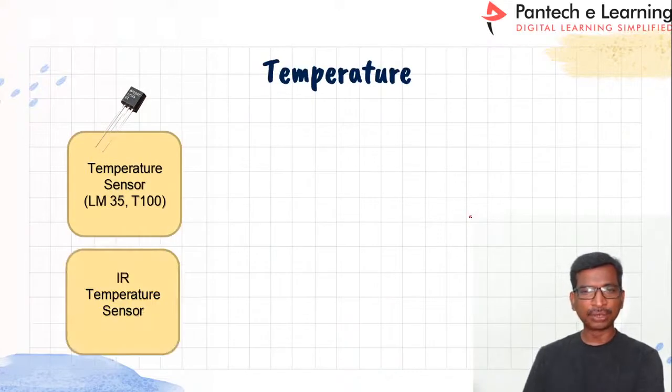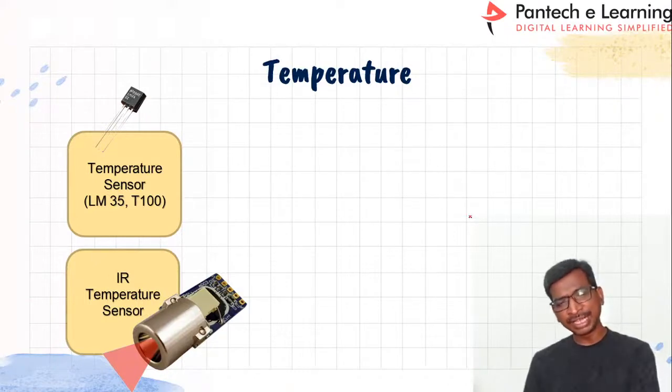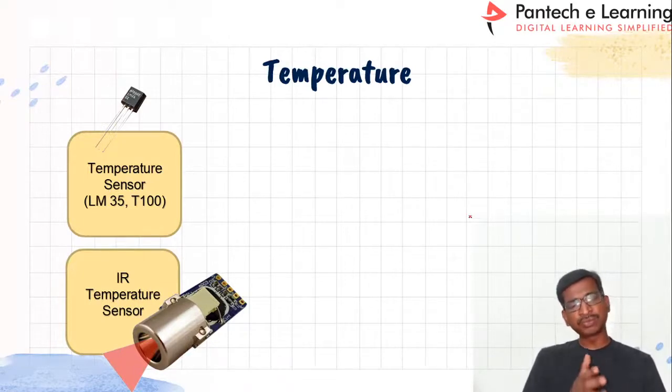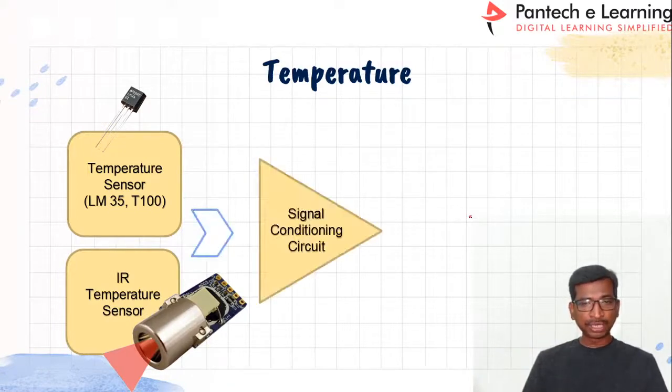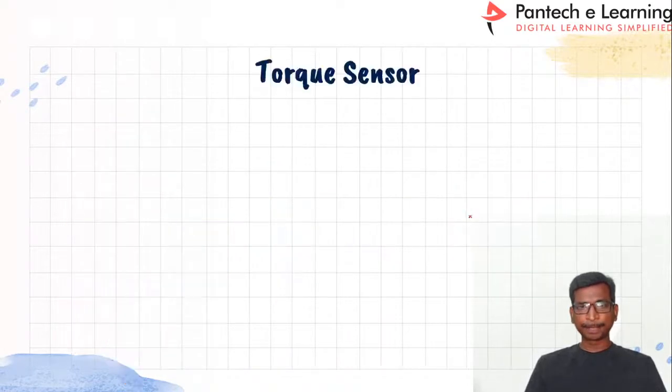And then the temperature model. So here the temperature models are the LM35 and then PT100. So these are all the basic sensors, and another sensor is the IR based temperature sensor. So these two are widely used. Again, based on the applications, you have to use different types of sensors. So whatever the sensors, see here, the same signal conditioning circuit we have to use, to get the desired output voltage, right?